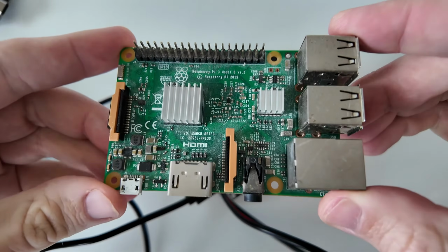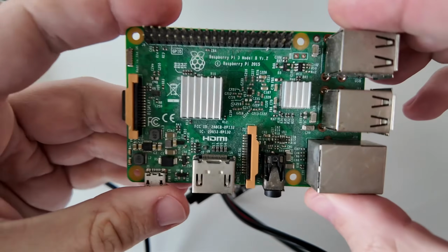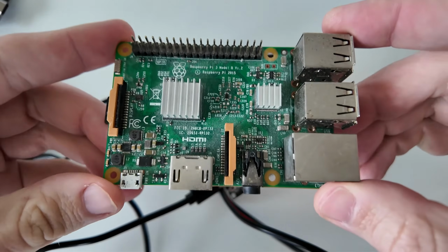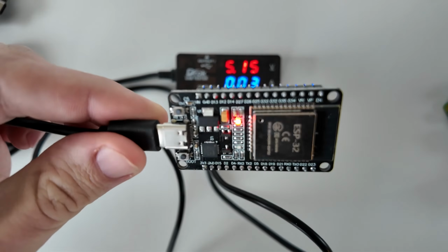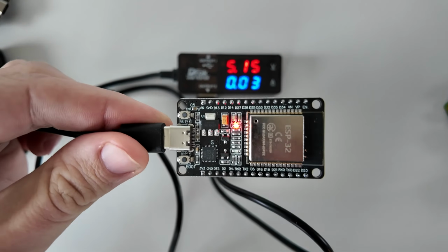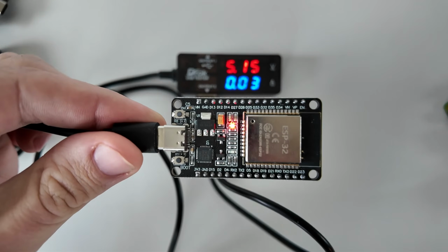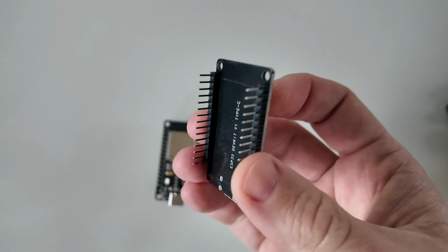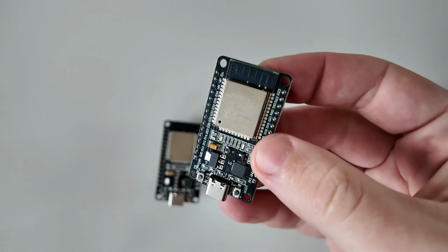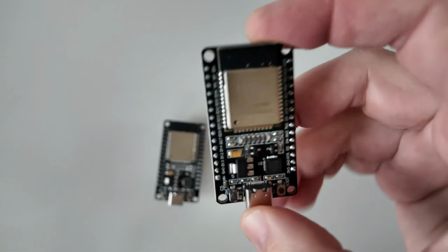Raspberry Pi is also a full-fledged Linux computer, so it can be a source of security risk. If someone gets access to the Raspberry Pi, they have full access to your home network. Compared to that, an ESP32 is a bare metal project, it just has no OS inside. Nobody can do an SSH login to it because there is no SSH, it's easy. And it also has plenty of ports, we can do lots of things. We can connect GPIO, we can connect Wi-Fi, we can connect external devices.